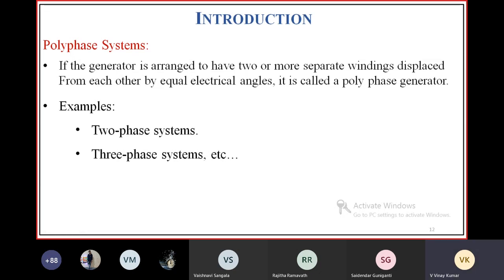Coming to the three-phase system, anyhow this is a polyphase system as well as the other. The three-phase system is the same as this, but it has three armature windings. Two armature windings will produce two voltages, and three armature windings will produce three individual voltages, provided that we rotate all armature coils inside this magnetic field, producing three armature winding voltages.